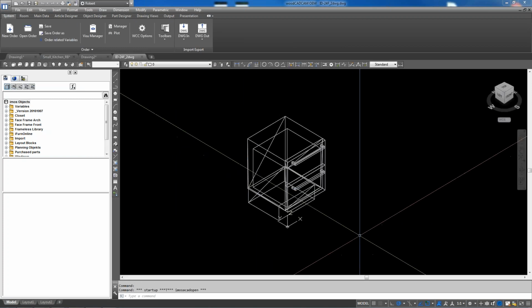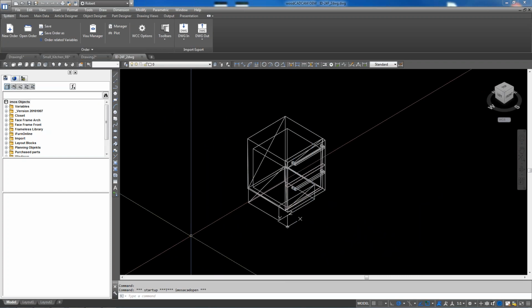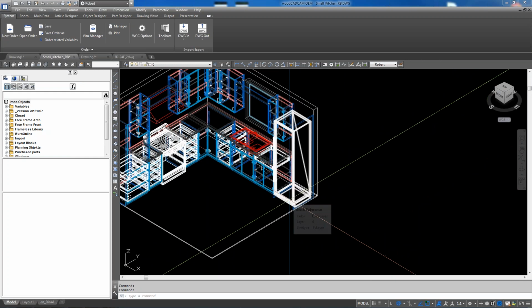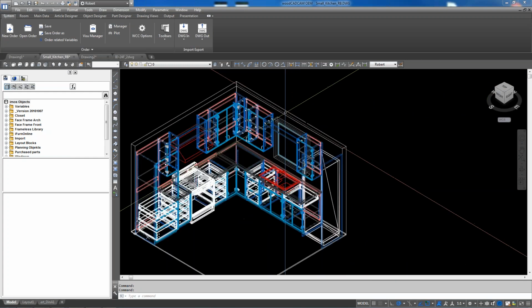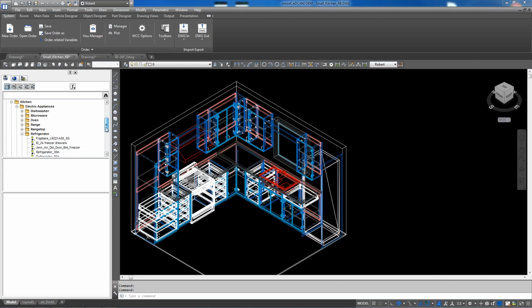Okay, let's get rid of the one we made earlier in the layout block. Open the layout blocks in kitchen refrigerators. This one? No. On your WoodCAD cam manager in your library, layout block, kitchen refrigerators. Select that one that you made, right click on it and delete it.